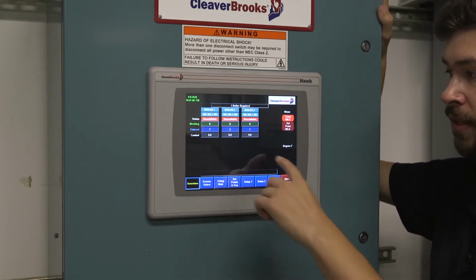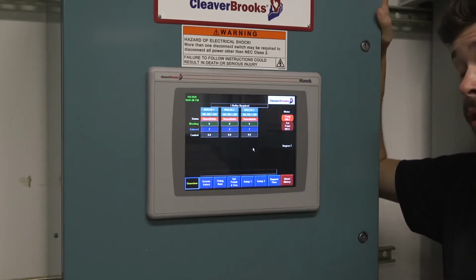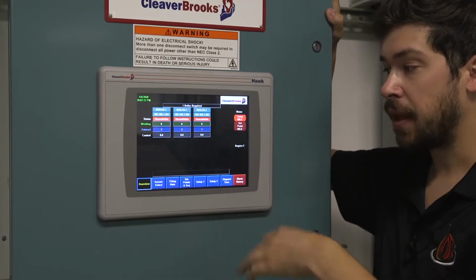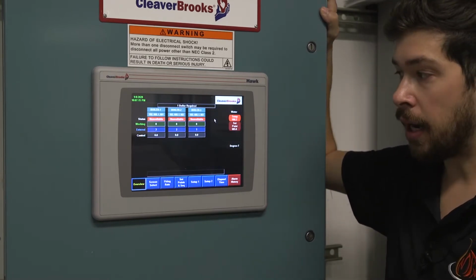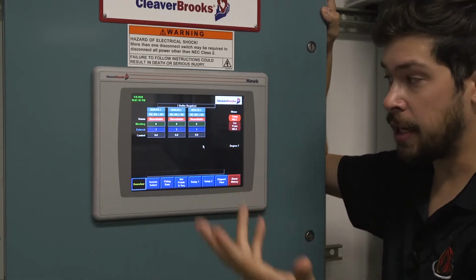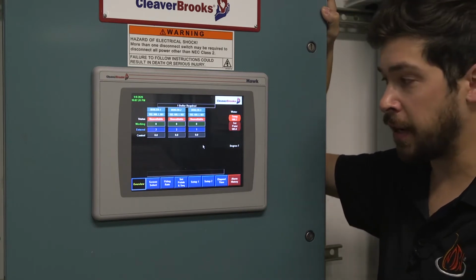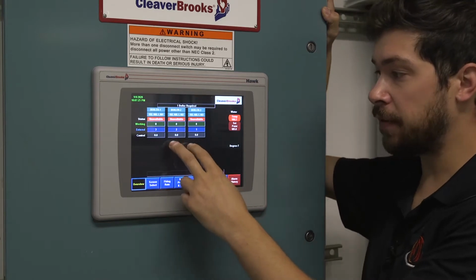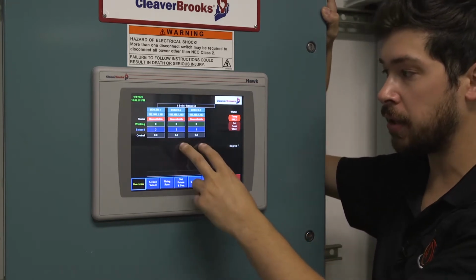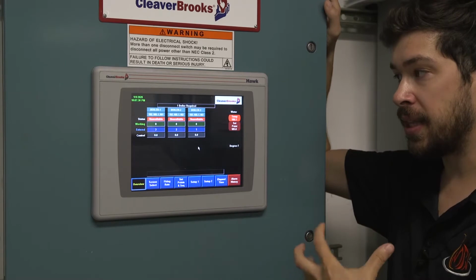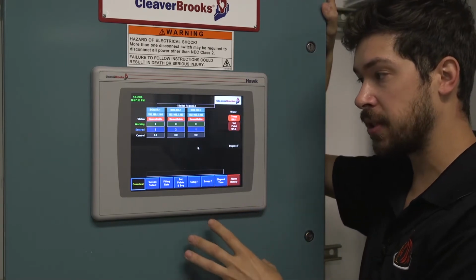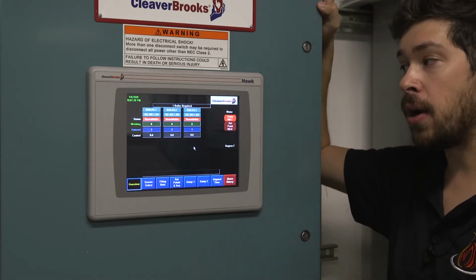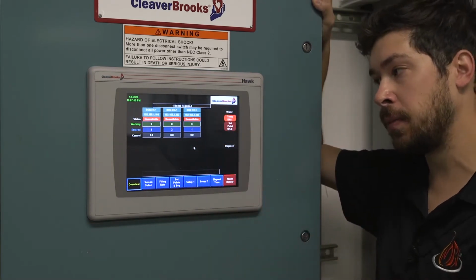This control at the bottom is going to be how hard each boiler is firing. So that's the firing rate. If it's 0 and running, then it would just simply be at idle. If it's running and 10%, then it's running at 10% firing. 100%, so on. The percentage of firing is the critical component as to this panel's thinking and processing in terms of, am I okay with 1 boiler or do I need 2 boilers?